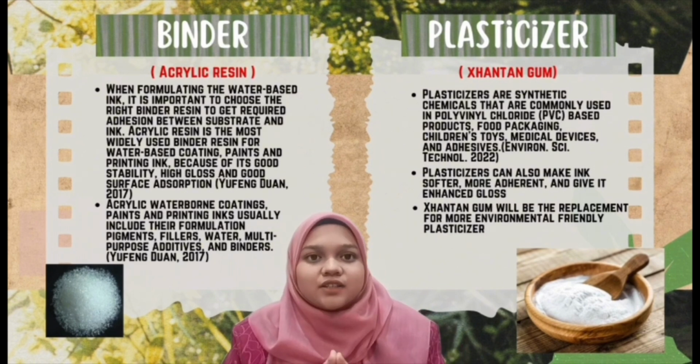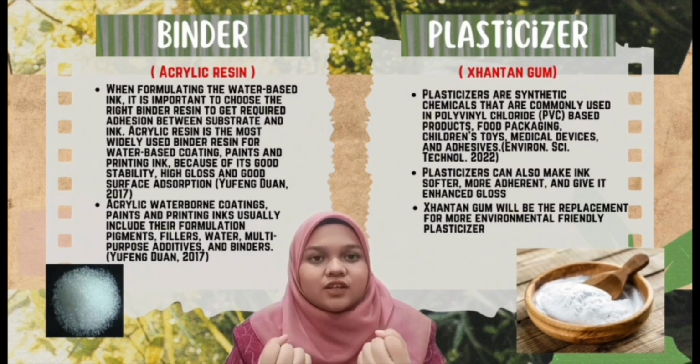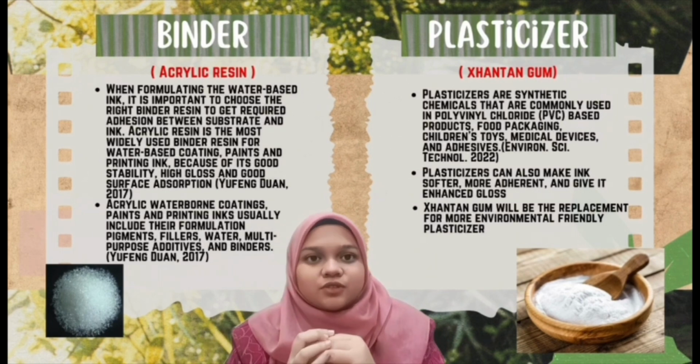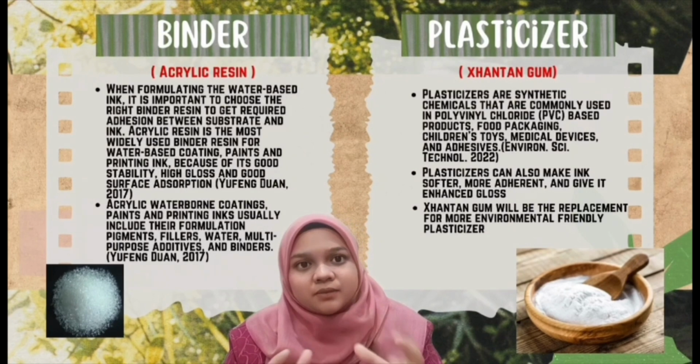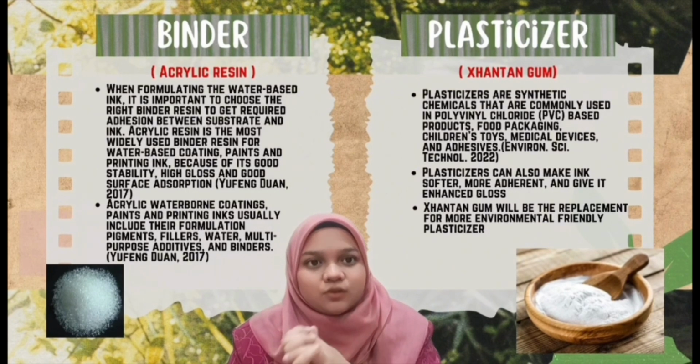Lastly, binder. Binder is the key component that holds the ink together and ensures adhesion to the substrate. In this project, we use acrylic resin as binder. Binder helps form a durable ink layer by binding the pigments and fiber while maintaining flexibility and wash resistance.